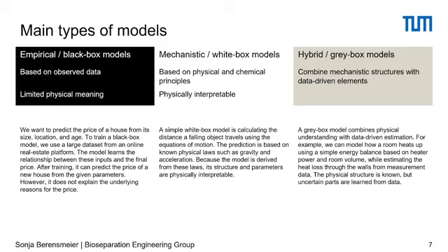You can describe this using some simple energy balances given the output of your heater and the volume of the room. However, things like the heat loss through the walls are quite complicated. The walls might have different geometry, might be built of different materials. So we could try to approach the heat loss part of our model with a data-driven solution, while the volume and the heat input are derived from a model-based system. So this is how we can have these combined hybrid gray box models.